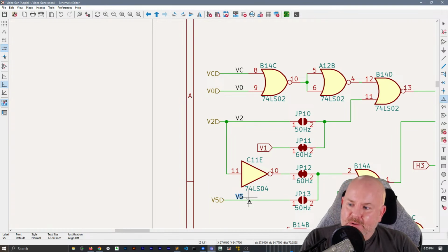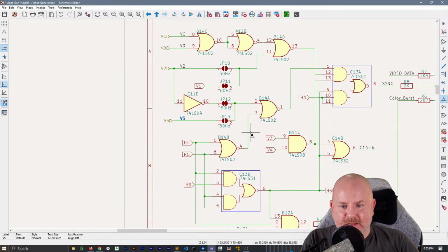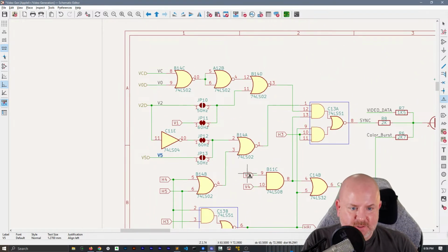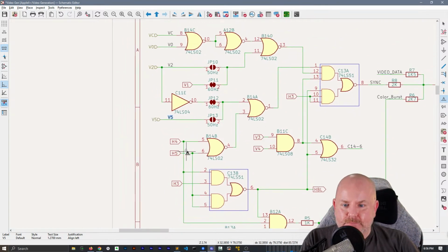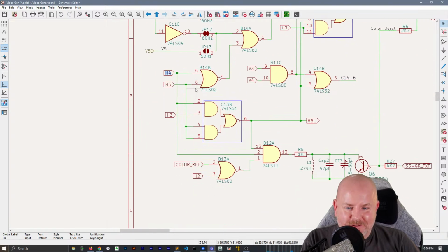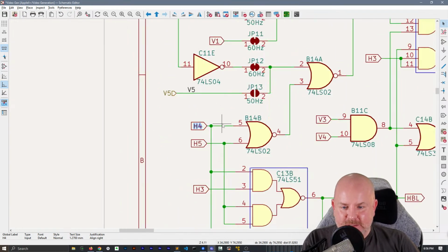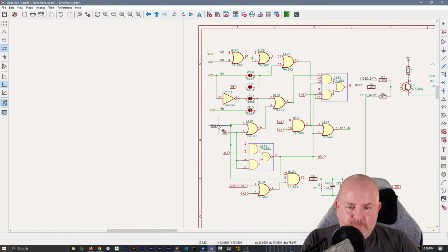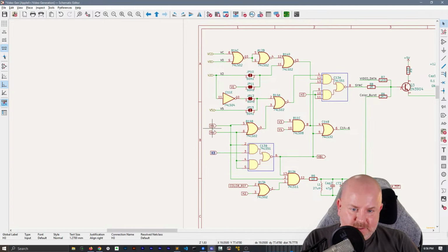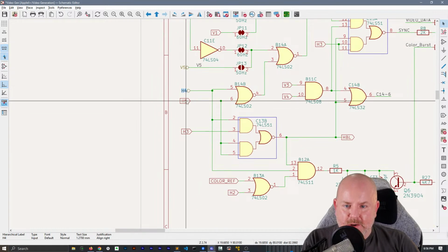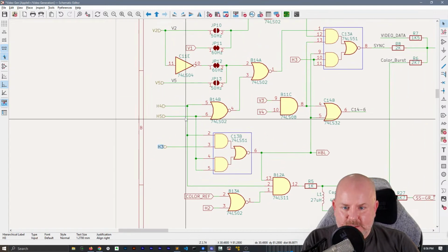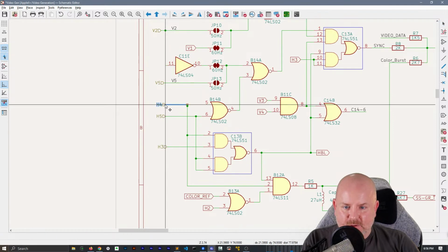Yeah, I saw your thing in the Discord about the tube tester. I don't have anything to recommend there, because that's not something I have done. In terms of an isolation transformer, just get a decent quality one. Don't just get the cheapest one on Amazon. And remember, isolate your DUT, not your test equipment. You can buy a new scope or whatever. Scopes are a little more expensive.